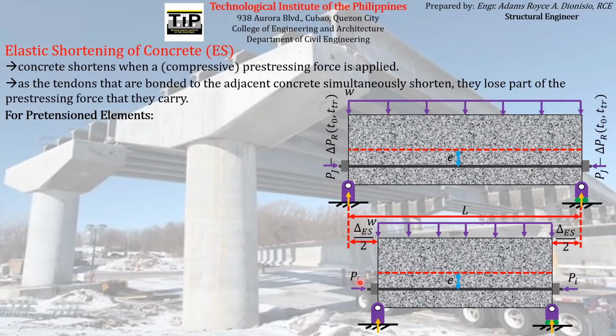And again, that is the pre-stress force that resulted when you deducted the pre-stress loss due to the elastic shortening of concrete from the magnitude of force that is being transferred by the pre-stressing reinforcement to the concrete element at the transfer stage.